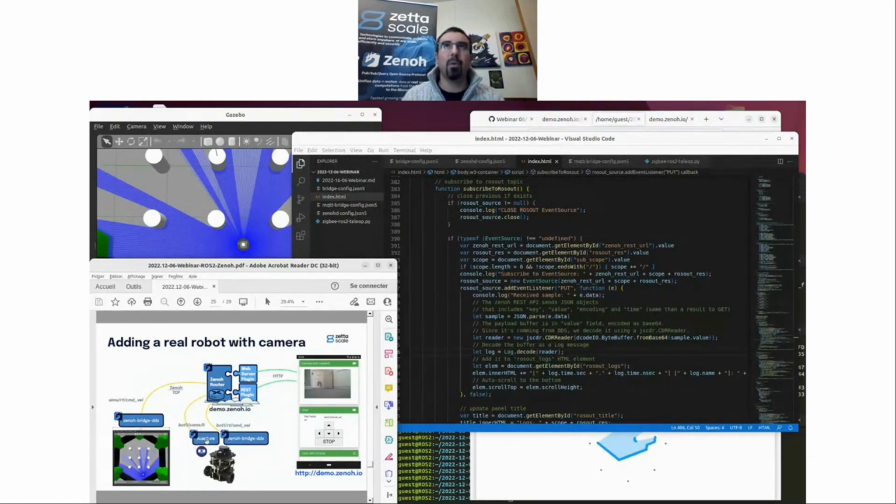In the GIST README description, you have the links to the GitHub repository where you can see the code of this Z-capture, and you can also build it directly on your robot if you want. So this Z-capture Zenoh application is publishing each camera frame directly on a Zenoh key expression named bot1/cam/0. And in the Zenoh router, I will add a web server plugin, which is slightly different from the REST plugin.